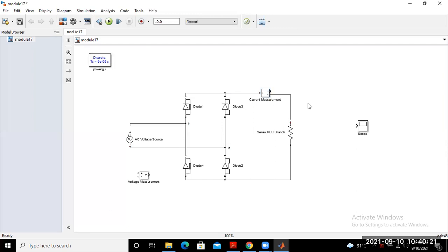Now you may require another voltmeter for the measurement of the input voltage waveform and output voltage waveform. So one more voltmeter you required. So just create from here another voltmeter. So move this one up to this point, and this voltmeter you may connect by rotating this one. Okay.